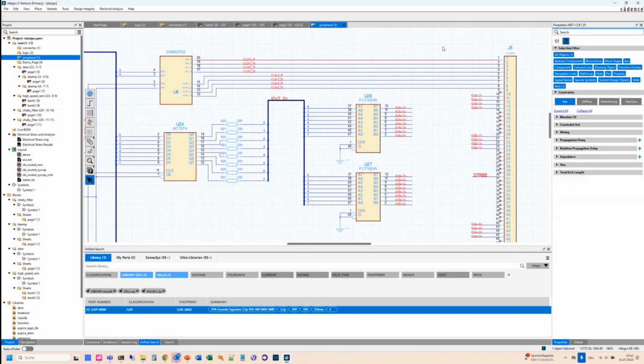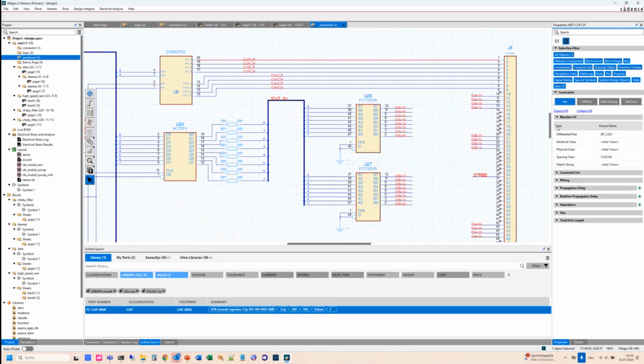You can now go directly into that, and then you can see this clocknet is part of this differential pair clock 1, and on this net there's an electrical CSet diff, a physical CSet like default, and a 300 micrometer spacing constraint set. So you directly see everything.